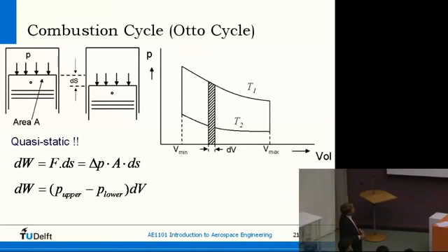Well, if we do this, you can say that this is the amount of work being done by the engine at high temperature when it expands, and this is the amount of work being done when compressing the air. And the trick is, of course, the temperature difference. So when you expand at a higher temperature than what you compress, then you get a net difference of work, and this means that the area of this PV diagram, this area that's enclosed, is basically the amount of work that the engine performs at 1 stroke. So if you know the strokes per minute, then you can also count the power.